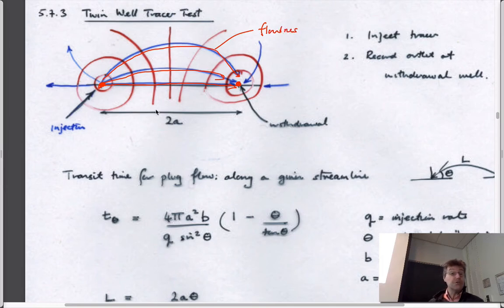These blue curves, which I'm overwriting, would be flow lines. So this is just a potential flow net, which again you should also have dealt with in 452. The lines that cross those perpendicular are equipotentials.